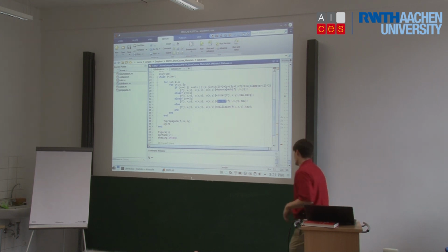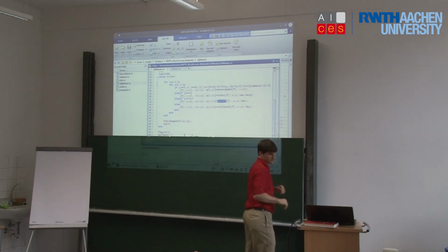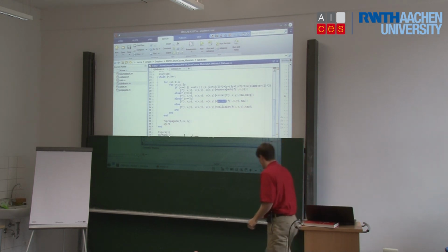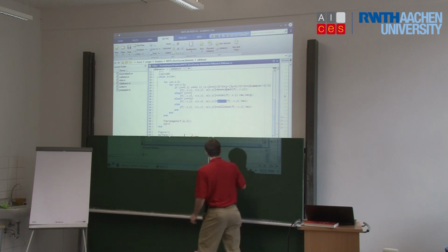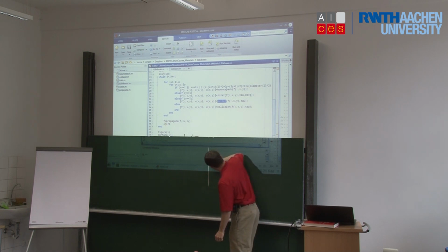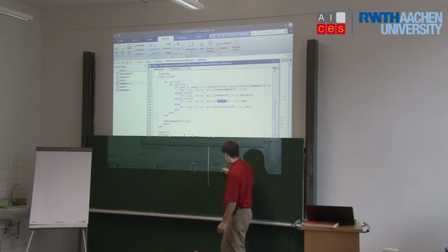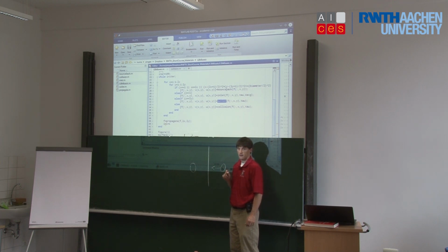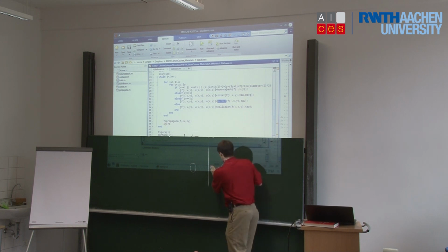So we have a solid boundary. And if we're looking at particles, there's a node on the other side of the boundary, and there's going to be a particle that's moving from here to there. Well, what will happen when it hits the boundary? It depends a little bit on the boundary properties, but if we have a no-slip boundary condition, this particle is going to hit the boundary and it will reflect back.